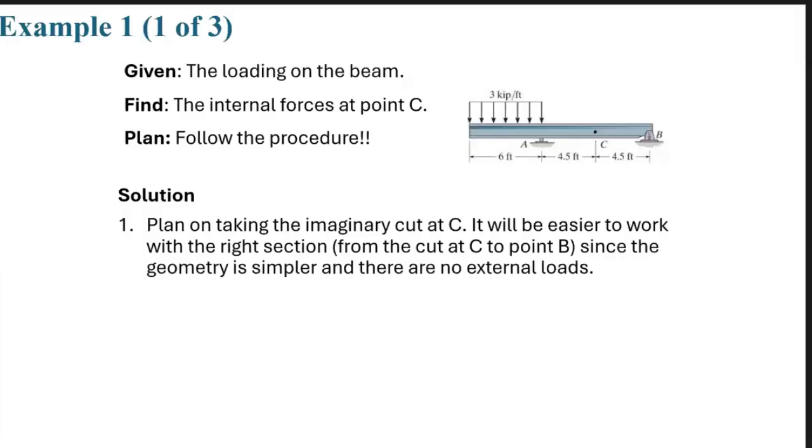Example. Now let's go through an example. We are given a beam with certain loadings. You see that there is a uniformly distributed load between point D and point A. And we want to find the internal forces at point C. First, place a cut at point C.